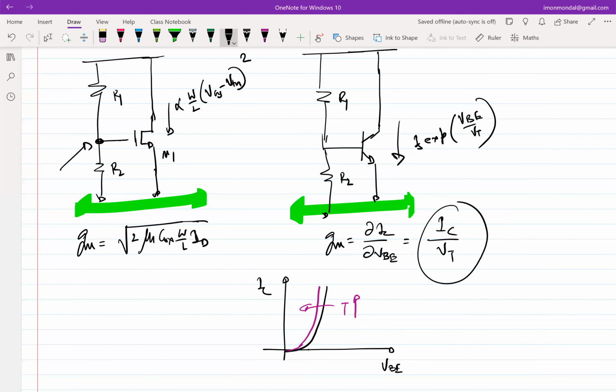Well, primarily that will not help, because the current is not primarily dependent on whatever is connected on the collector, right? Just like in a MOSFET, if you connect a resistor to the drain, it doesn't really affect the current. It will go out of your region of correct operation. Yeah, so that you don't want, right? Okay, it will probably not burn off, but you'd also want to make an amplifier, right? So you don't want to do that. Among all the biasing techniques that we have learned, which one do you think is more appropriate to bias a BJT?